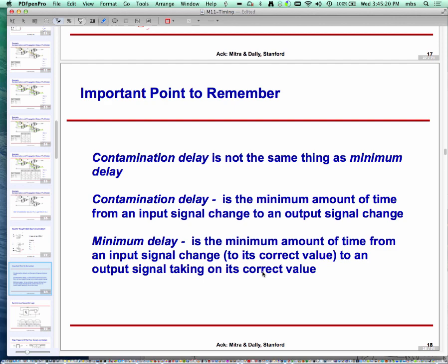So what's the minimum delay for an n-bit adder? Minimum delay is something we were not keeping track of at all, but it is at times useful. Usually propagation delay might be a function of temperature. It may be that when my chip is hot, propagation delay is higher than when the chip is cold. So the manufacturer may say that across the operating environment, at this temperature you might see this propagation delay, at that temperature you may see that.